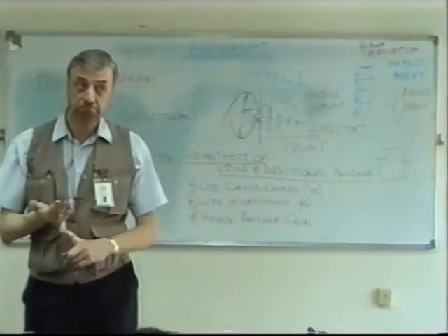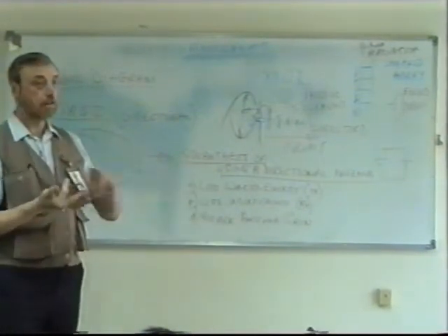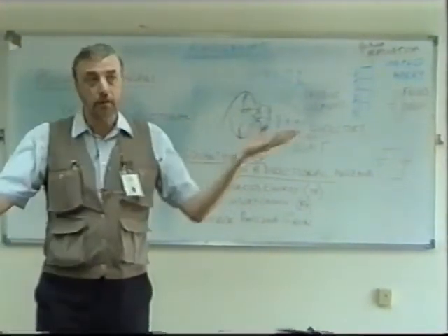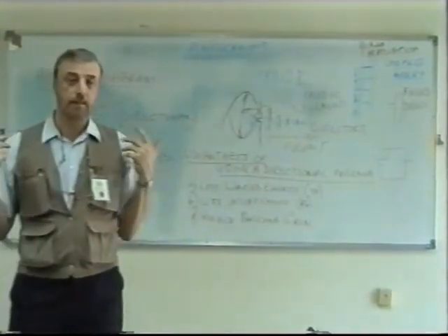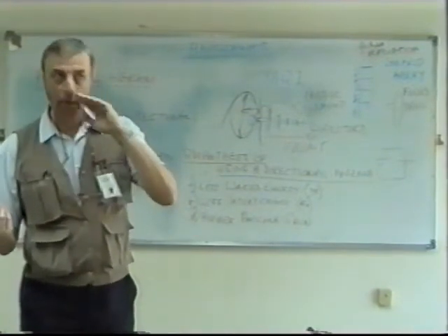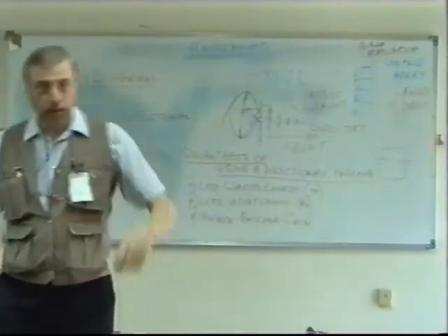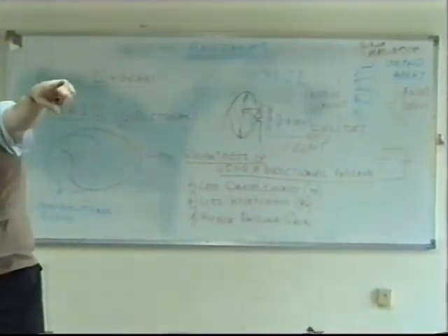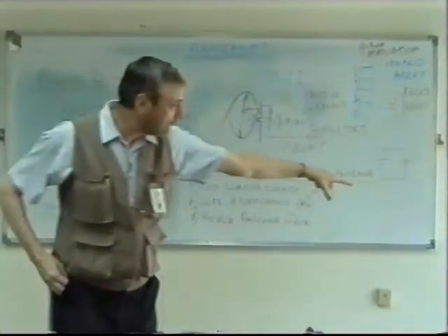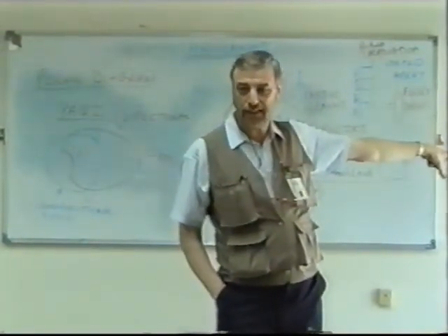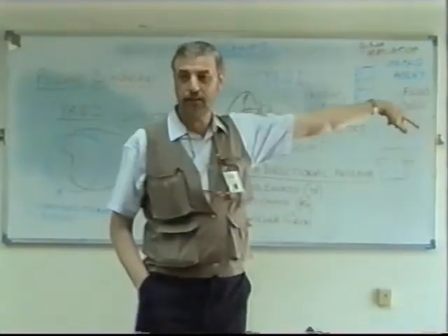Now, power and how directional your antenna is, the polarization, all this is to cut out interference in the case of a receiver and to stop wasted energy in the case of a transmitter. But in all cases, the actual range depends on whether you can see it or not. If you put an antenna on top of one of those hills over there, I can see that hill, so I'll communicate. You could put an antenna down here in one of these streets, and I can't communicate with you, because it's hidden behind buildings.